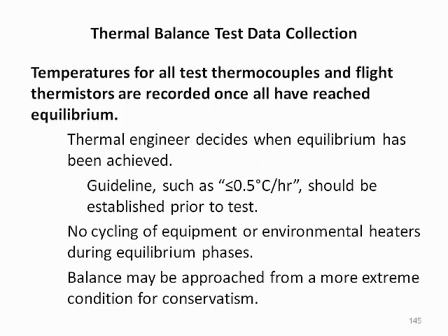For each thermal balance phase, temperatures for all test thermocouples and flight thermistors are recorded once all have reached equilibrium. Ultimately, it is a thermal engineer that decides when equilibrium has been achieved, although a guideline, such as less than ½ degree C per hour, should be established prior to the test. No cycling of equipment power or environmental heaters is usually permitted during equilibrium phases so as to achieve a true steady state.